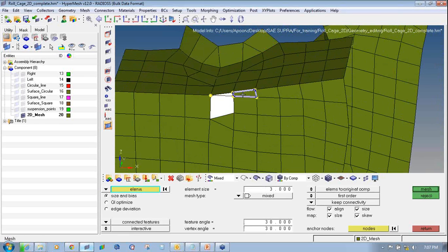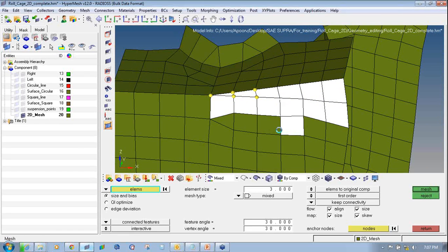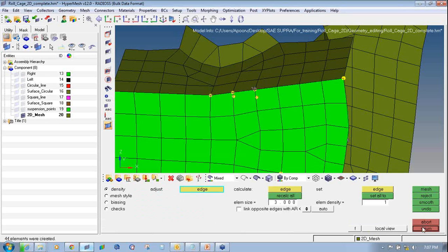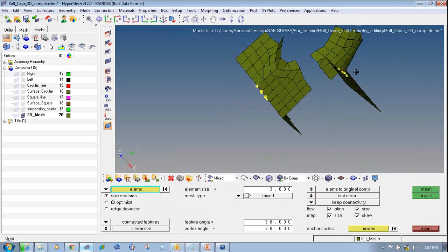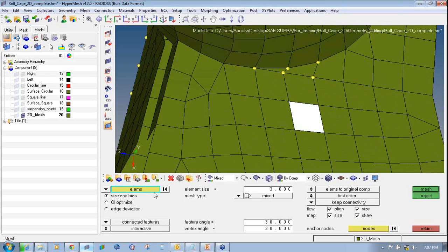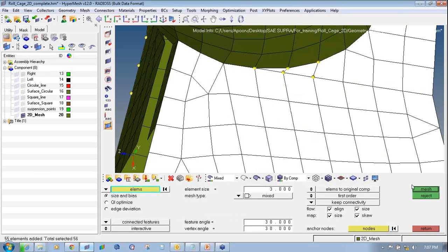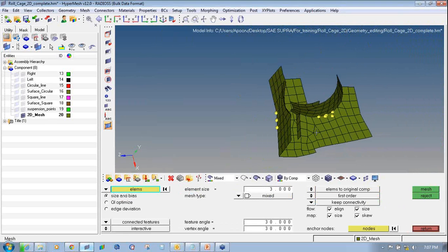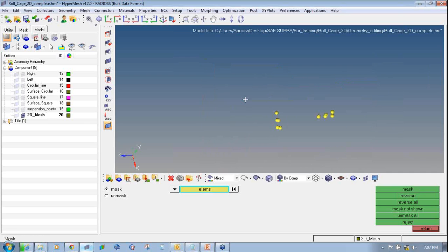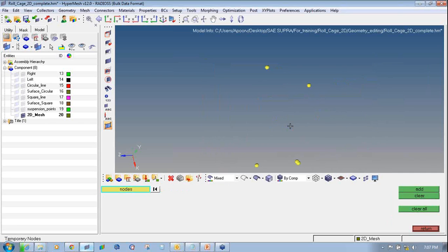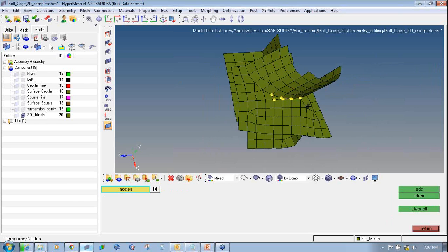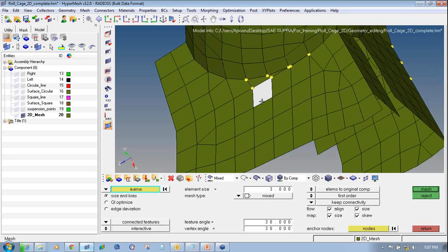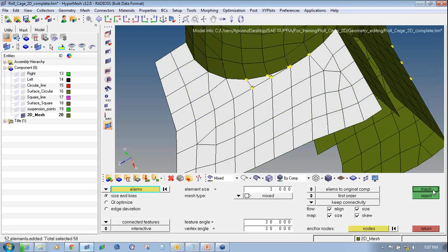Then this thing can be removed by manually meshing it again. So mesh by face and say mesh, return. Similarly on this end, pick any element by face, mesh and return. F5, mask this, shift F2, clear. Similarly this side also, F12, pick any element by face, mesh,